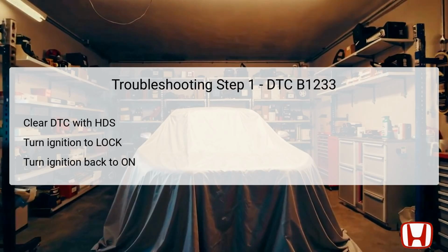Subsequently, the ignition should be turned back to the on position to energize the vehicle's electrical systems again. This step essentially resets the climate control unit, allowing for a fresh self-diagnostic check. It is crucial to perform this step carefully, as skipping it may lead to incomplete diagnostic results.